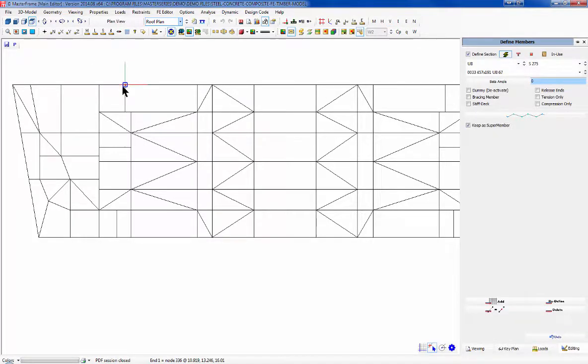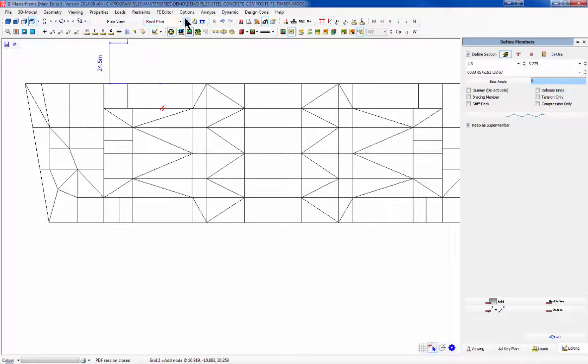and you've got node points, so I could put a bracing member in there if I want to, and it clicks on it. I can easily say I want to go from the center point to the center point of that member, but obviously that wouldn't be right, so I would go from the center point either to the center there or perpendicular, and I'm just going to do an undo there.